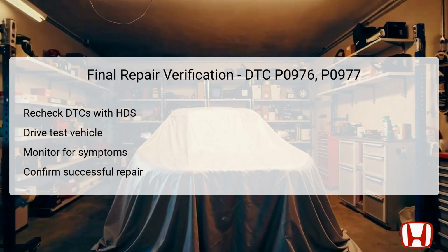Following this verification, it's crucial to undertake a drive test of the vehicle to observe its performance under real-world conditions. During the drive test, pay close attention to any transmission-related symptoms that were previously noted or that may arise. Ensure that the vehicle transitions smoothly through all gears and that the shifting behavior is consistent with standard operations. If no new DTCs appear and the vehicle operates correctly, you can confidently conclude that the repair has been successful.